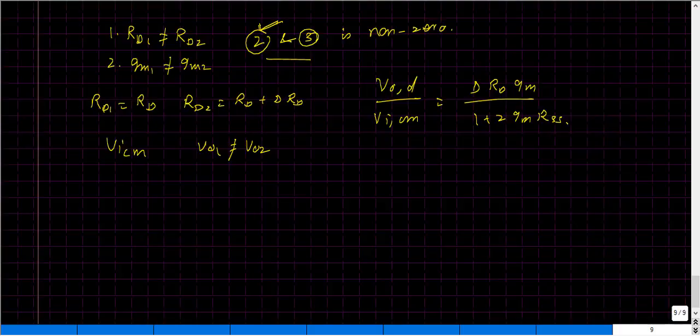Okay, we know when the circuit is not symmetric, what happens when we apply anti-symmetric inputs. As I stated before, for an anti-symmetric input applied to an asymmetric circuit, the common node will not be driven to ground.